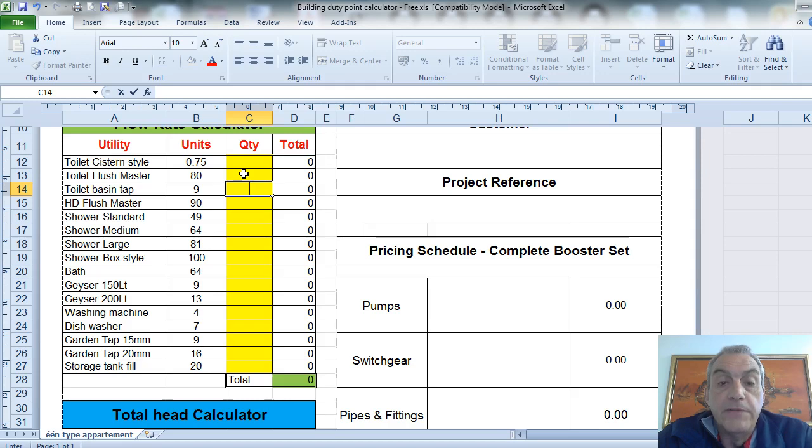What it does, though, that's very different to a normal toilet cistern, is that it refills the void of potential water to do the next flush. It does it very quickly. Why? For argument's sake, if you were at a high traffic area like an airport toilet, or a sports complex, let's say you've got 400 guys all standing at half time waiting to use the toilet, you can't have people using normal cistern style toilets where when you flush the toilet it takes up to 25 to 35 or 45 seconds to refill the toilet.